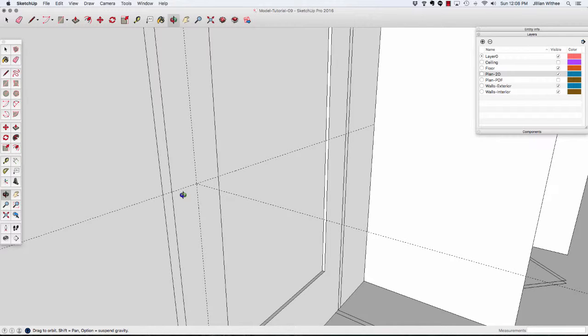Now let's create the back plate of the doorknob. So click on your circle tool, either in the large tool set or the toolbar. Click on the center of those guides, that intersection, and you can see the red X appears and you've got a green circle showing that that's where you're going to be drawing your circle. And you're going to click on it, and the number that you enter is the radius. So we want to create a 2-inch back plate. So type in 1 inch and hit enter.